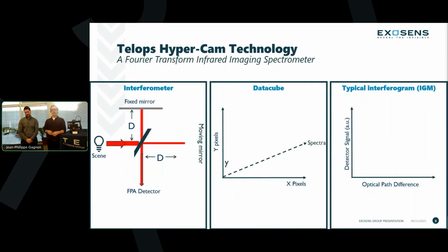So, just a few words about the inner workings of the camera, to help you understand a little bit more how the data is being produced. Inside of the Nano, just like our other members of the family, sits a Michelson interferometer, or a Fourier transform interferometer. This is a special type of optical equipment that has a beam splitter in the middle. It's all based on the interference of light waves. The light waves come into the camera and split into two paths, or two arms, and we vary in one of the arms the distance between the mirror at the end and the beam splitter.